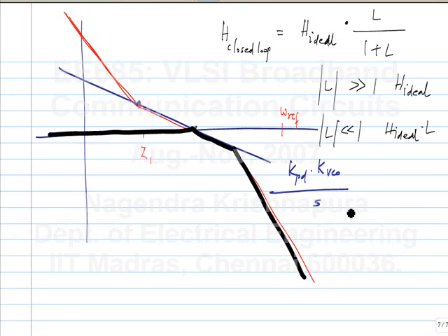So this now gets us the best of both worlds, that we have an integrator for the phase detector. So that means that we really have an infinite lock range. We will see that in a moment. And we can also introduce further attenuation poles between the unity loop gain frequency and the reference frequency, okay. That will further increase the attenuation for the reference feed through, okay. So we can clean up our output phase, as well as increase the lock range. So this is the classic PLL that is used. This is the practical PLL that's used.